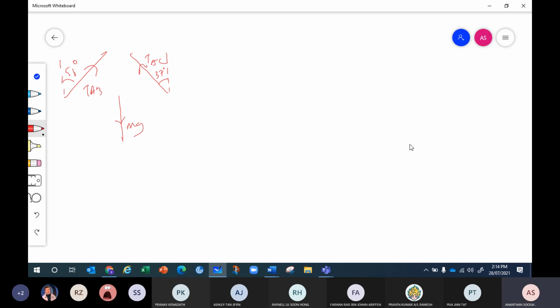Remember, when you want to make a triangle, first go and draw the vectors which are perfectly vertical and horizontal first. Finally, diagonal. So here I prefer to draw MG first. Second, any one of them will do because both are diagonal, so it doesn't matter. So I draw MG first, MG acting down. First vertical. And the tip, you have to make a closed triangle, because it's in equilibrium for sure. So you can join the AB or AC one.